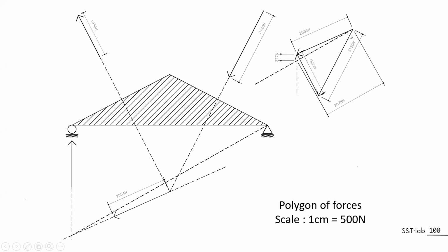To position all these forces, that's very easy. You know that the resultant applied forces are supposed to have an intersection point here. You know this direction, and so from this here, you will know the intersection point with the vertical force. This intersection gives you the direction of the last support force. I was decomposing it here, but I don't have this information at the very beginning. I have the resultant forces here.